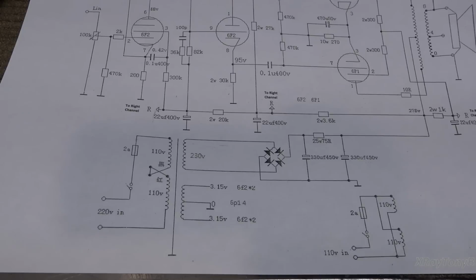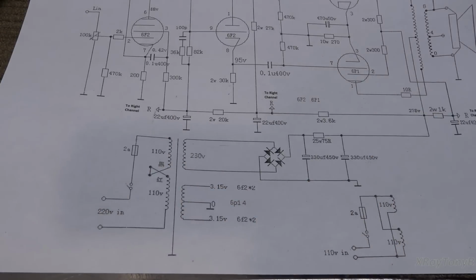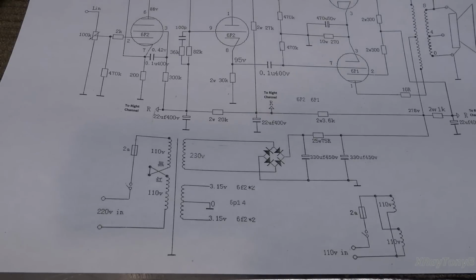For instance, even your meter, when it is measuring, let's say, voltage, you have to have current flowing through your meter or through your test equipment to be able to see the voltage. And vice versa, there has to be a voltage potential present before any current can flow through anything, including your meter or any piece of test equipment. So when people say AC and DC, they're just meaning that the energy that's there is flowing in either one direction or in alternating directions back and forth. And we'll see this here in just a minute.